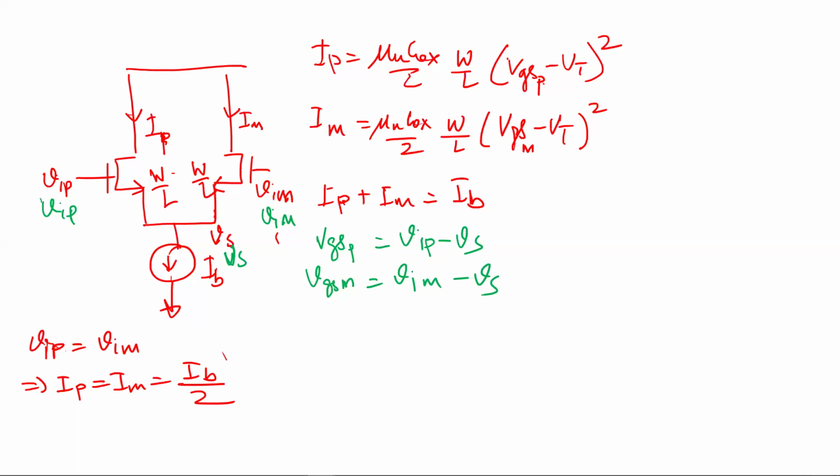So that's when this is the same. So let's say I started with 0.9 volt, like I said, right? So 0.9, 0.9. So this is 0.9 volts. This is 0.9 volts. So what had we calculated this to be in that source follower? 0.3, right? Let's say IB is 50 microamp. So in that source follower, we had calculated, sorry, this has to be 100 microamps.